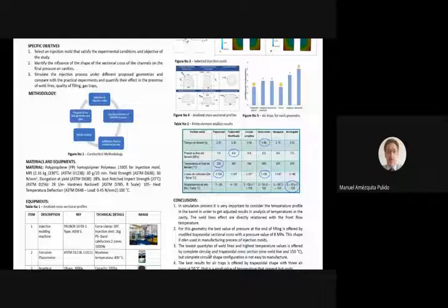We used polypropylene homopolymer Polymax for injection molding that has a melt flow index of 30 grams in 10 minutes, a yield strength of 36 newtons per square millimeter, elongation at yield with a value of 28%, an ISO notched impact resistance of 28 joules per meter, and a hardness level of 105. Heat deflection temperature 100 degrees.